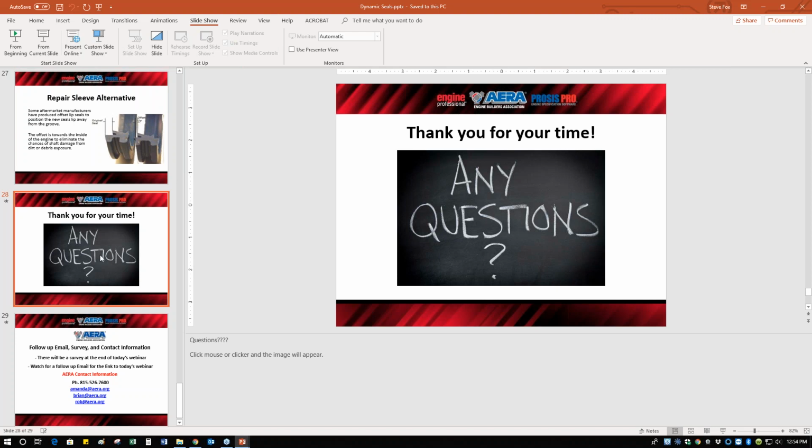Okay. Another question: is there an easy way to determine what material a given seal is made of? Unfortunately, no, there's not. You can't go by color because that doesn't really mean anything. FKMs are usually a brownish red in color, but that doesn't mean that what you're looking at is truly FKM. So the answer is no, there's not an easy way. We would use what they call an FTIR machine, spectral analysis, to determine what the compound is, and it's an expensive piece of equipment.